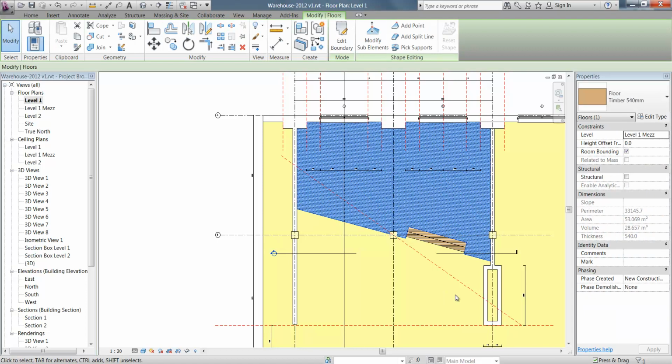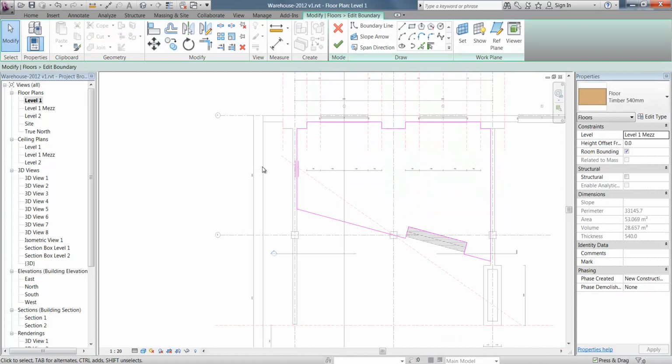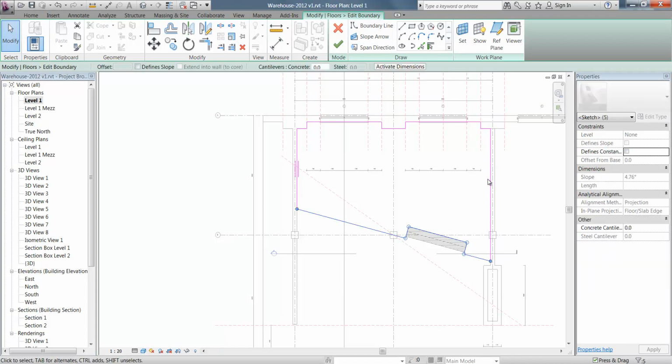And so now I'm going to rotate these elements that I've got, the floor and the stairs, that need to be aligned with that. So you probably know the align tool, but I'll show you some other ways. So with the floor selected, edit boundary will take me back to the sketch. Okay, so I'm going to select all the lines at the bottom here. Using a regular window, left to right, I can go over just those lines, and you can see there it's not selecting the lines either side. So I just want to make sure you know that one. That's a window, not a crossing window.